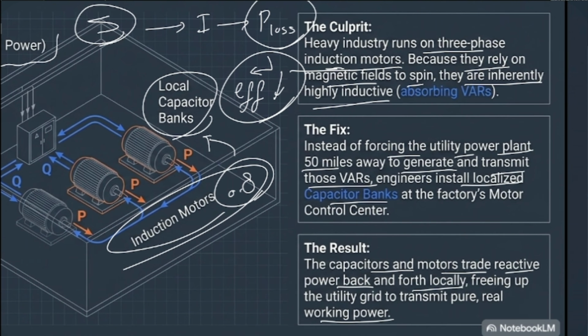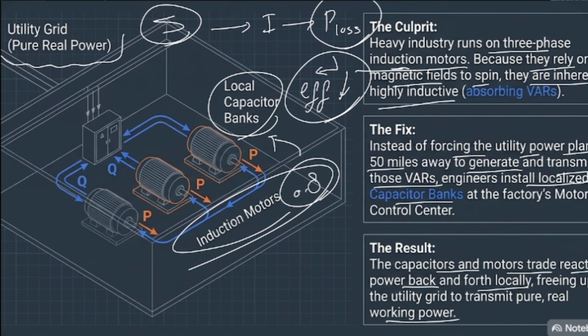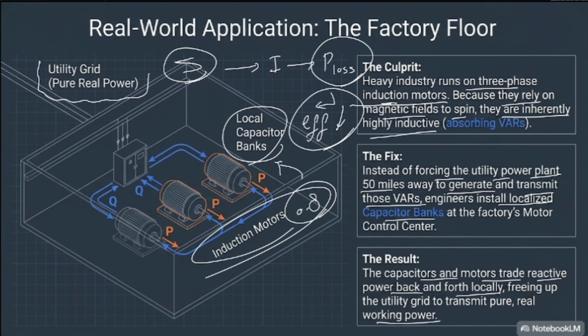So this means that we are happy, the power factor is going to increase, and the utility is going to be happy itself. One thing that I really would like to mention right now, that maybe you won't face in the future, is that reactive power has a strong relationship with the voltage itself. The active power has a relationship with the frequency itself. So when we are saying that Q is related to the voltage, another important fact that you have to consider is that Q is mostly localized.